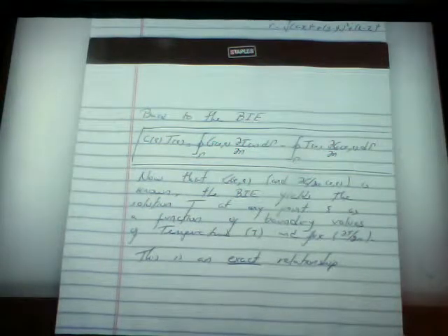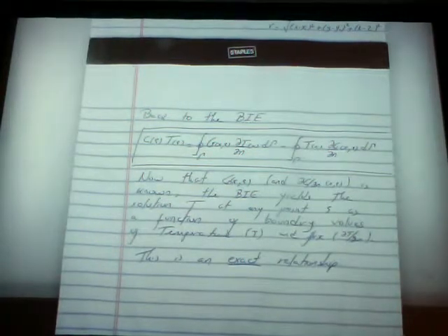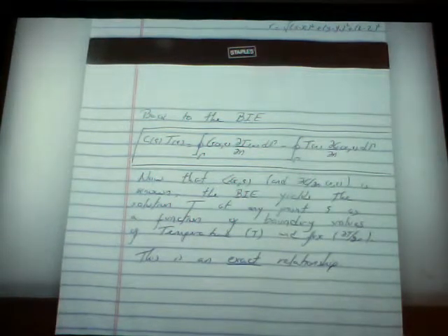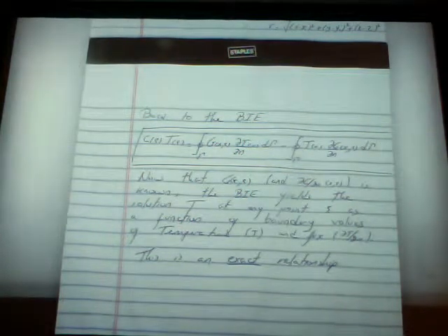We haven't introduced any approximation whatsoever, as opposed to any other numerical technique that relies on approximations, whether it's tessellation of the domain, subdomains, collocation, usage of polynomial shape functions. Up until this point, we haven't introduced any approximations. This is perfect, it's analytical, this is exact. That's why the boundary element method is more precise than other techniques.